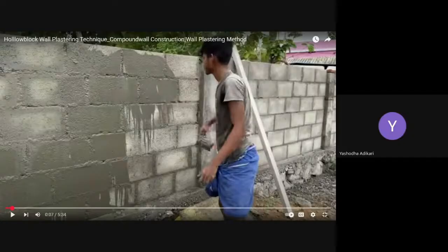If you go straight and apply this to a dry wall, the wall can absorb the water content in the cement sand mix. So what will happen then? When the wall absorbs the water from the mix you prepared, the mix dries out. You can't do that plastering in a good way. Right? You can't plaster properly, because the wall absorbs the water in the mix you prepared for plastering, and then the mix dries.